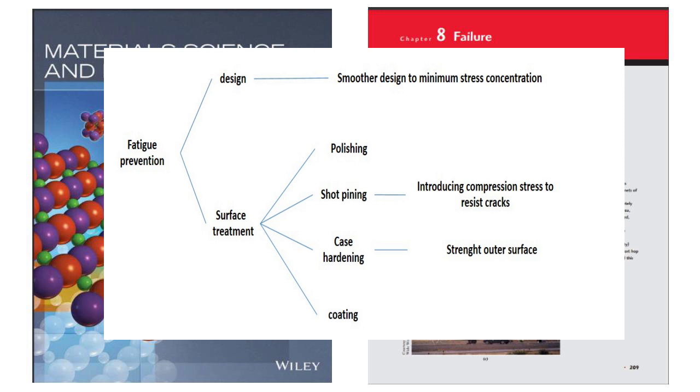Okay, what about protecting the surface itself? Surface treatments can be very effective. One common approach is polishing. You remove those tiny scratches and imperfections that can act as crack initiation sites. So it's like giving it a nice, smooth, protective layer. Yeah. And then we talked about shot peening. You're bombarding the surface with those little beads, creating those compressive stresses.